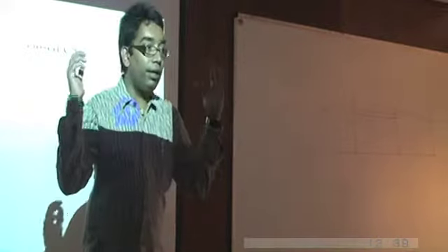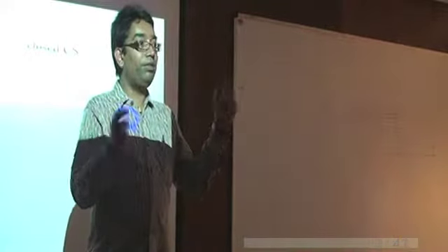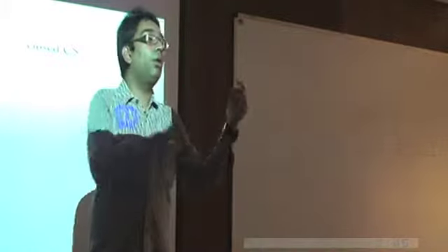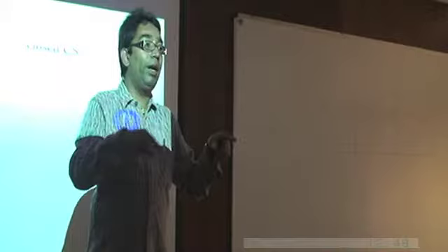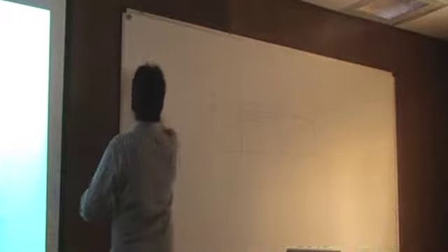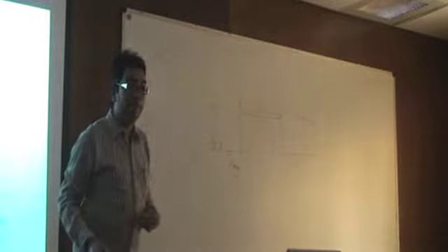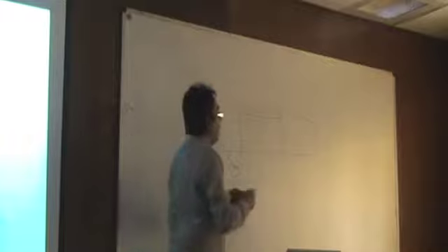So one of them is the bending stiffness, which relates, let's say, M2 with kappa 2 or M3 with kappa 3. It's basically a 4x4 matrix that we are talking about here, again into the same 1D strains. Now if you look at the 3-3 element here, S33 bar and S44 bar, those are basically your bending stiffness, right? So what is happening to this bending stiffness when you have a circular tube?